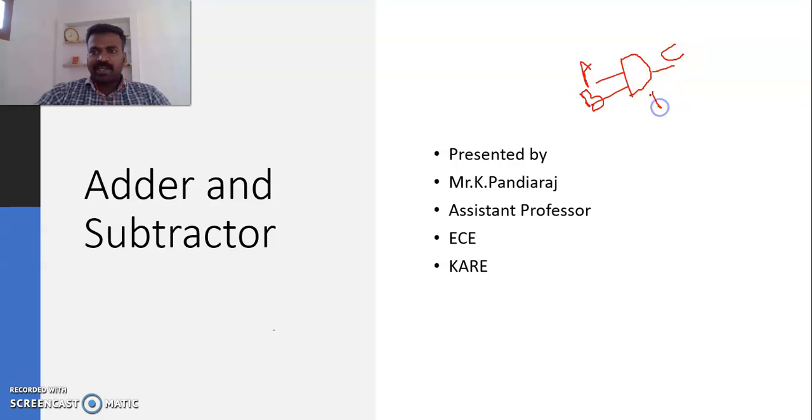So now this AND gate depends upon only this A and B. So presently if I am giving 0 1, it will produce one output, 1 or 0. When I change to 1 0, again it is going to change the output as 1 or 0. So the circuit depends upon only present input, not upon the past output. This is what combinational circuits are. So it depends upon only present input.